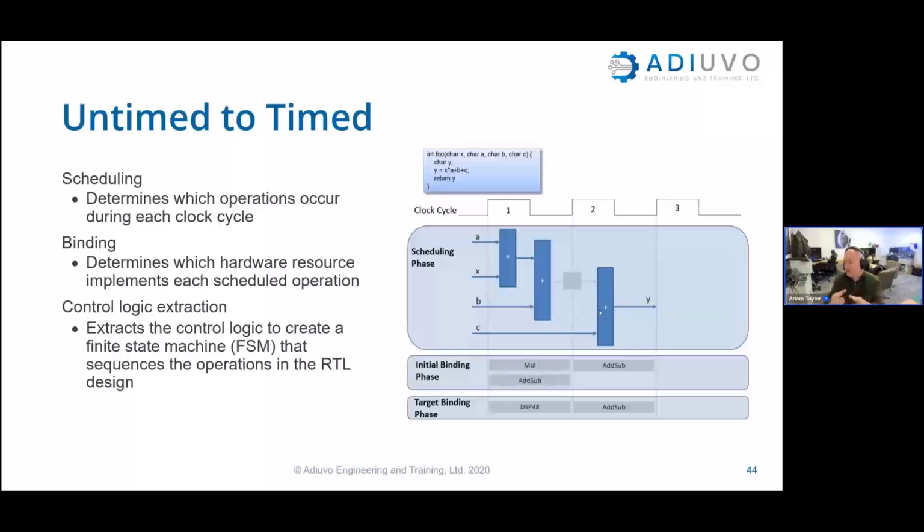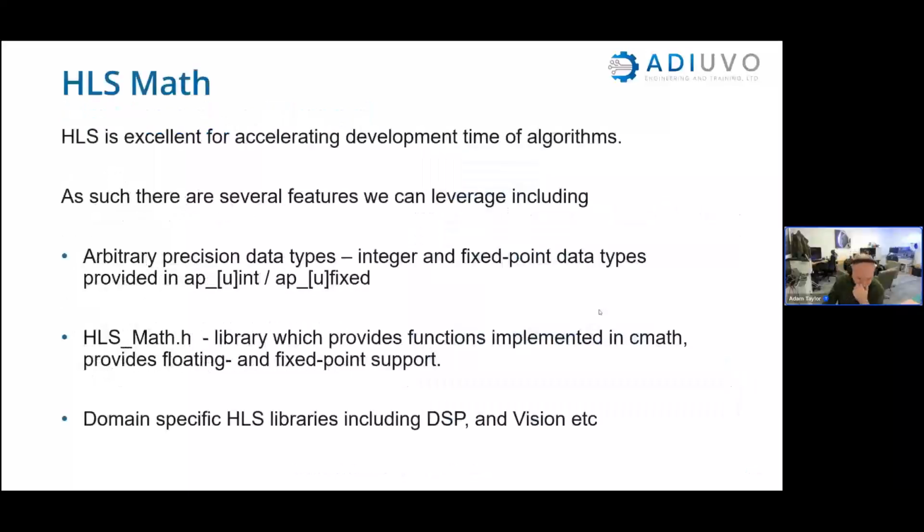And what we can do is easily change these interfaces to be not only discrete logic vectors or logic vectors with valid signals. One of the benefits of HLS is we can easily change these to have AXI interfaces, for example, or BRAM interfaces or filter interfaces. There's a lot of simple things we can do with it.